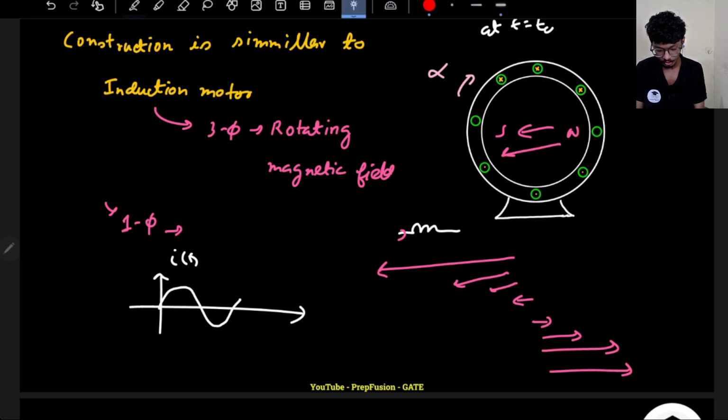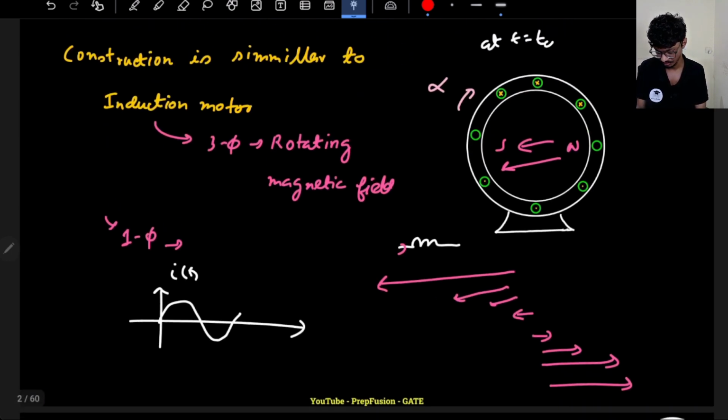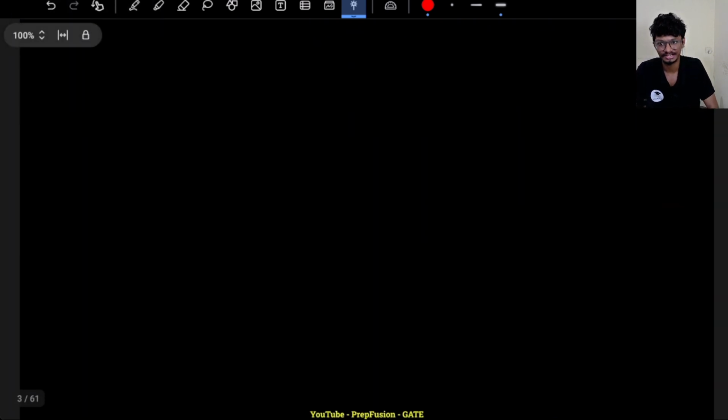What do you observe with respect to this point? The magnetic north and south poles are actually not rotating. The magnitude of the north pole's magnetic field is reducing, then again it is going in the opposite direction. The poles are interchanging basically, so the field strength will be pulsating in nature.